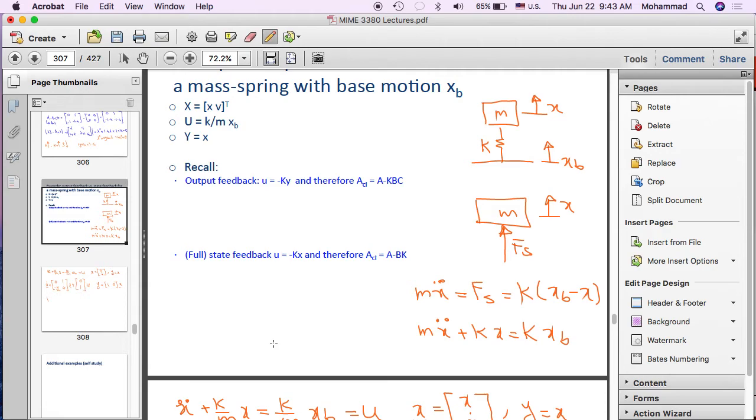You have a spring, it stores energy and it releases energy. Will that oscillation ever decay? What causes the decay? Is there a damping? So will that oscillation decay? No. So based on this behavior, what is your prediction? Where are the two poles located? So you have oscillation with no damping. Where are these two poles located?